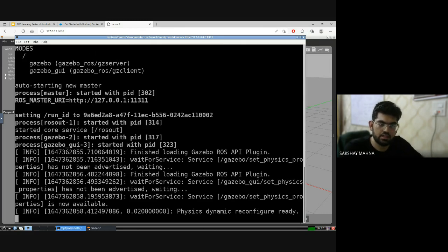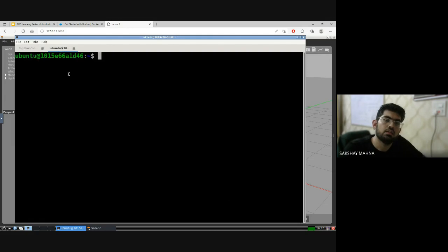I'll address that in a moment after I finish this. So we need to keep this tab running for the Gazebo simulation, and then we go over here. We click File, then New tab, and in the new tab we type this command: rosrun rviz rviz. Once again, you don't need to understand what the commands are doing. We're simply going to run them for now.